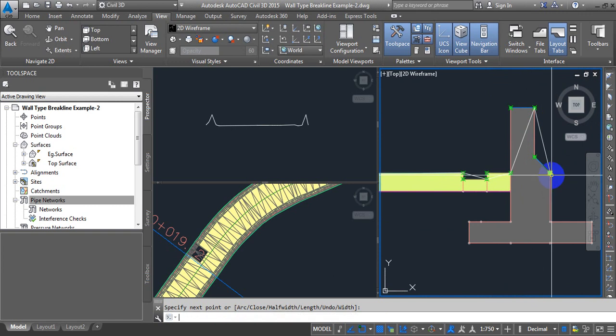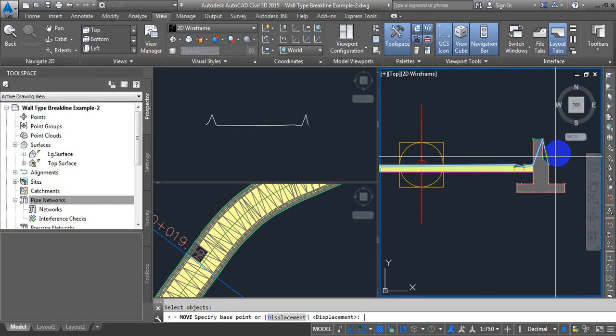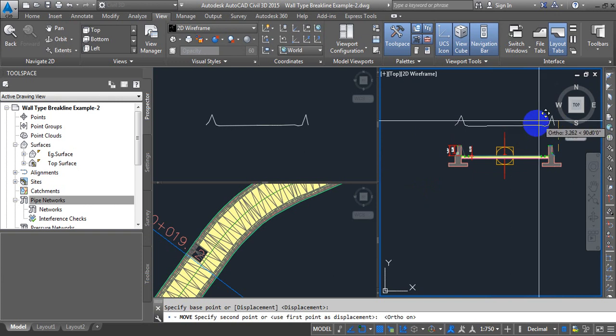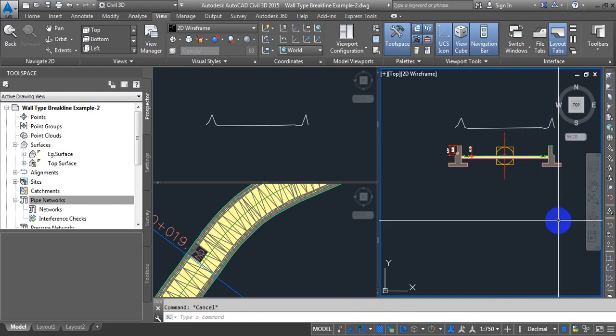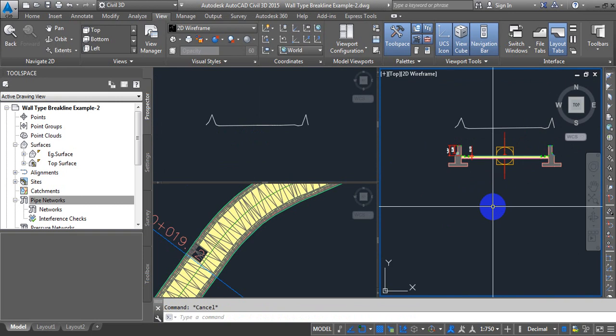And as you can see, if I take this line, this is exactly what I'm getting on the left side. Okay, so everywhere where we have these vertical faces, Civil3d is simply ignoring those points. Now how to refine the surface in such cases, or how to remove that inaccuracy, because we want to add this vertical face to our surface as well.